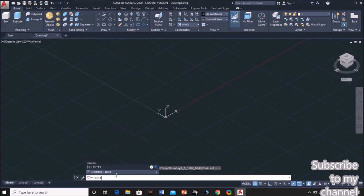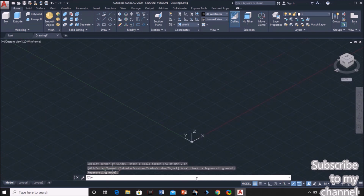Limits is used for setting the page. Now it is asking for the lower left corner, that is 0,0, and for the upper right corner I am giving the A4 size numbers, that is 210, 297. It is in mm, and click on OK. Next, to zoom the origin to center, I am using the zoom option. The command for zoom is Z enter and then A enter, for getting the origin to center space.